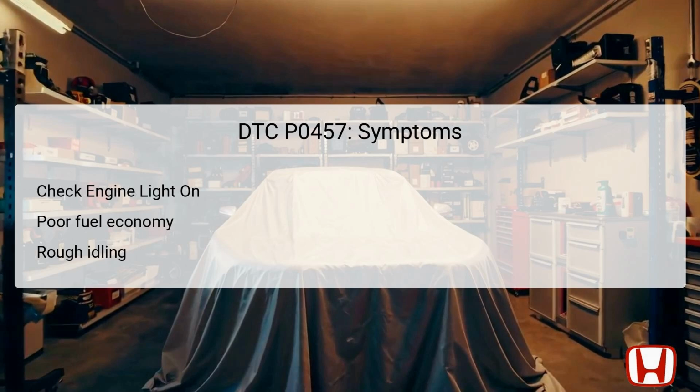Additionally, drivers may experience poor fuel economy since the Evaporative Emission Control System will not function efficiently due to vapor leaks. In some cases, you may notice rough idling, which can occur due to variable pressure levels in the fuel system. Another common sign is the vehicle failing an emissions test, which is critical for compliance with environmental regulations. Being alert to these symptoms can help in promptly diagnosing and addressing underlying issues.